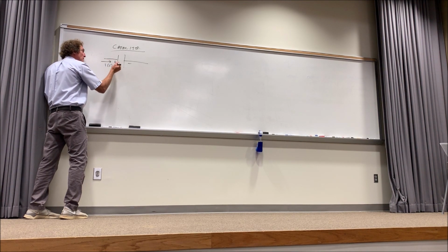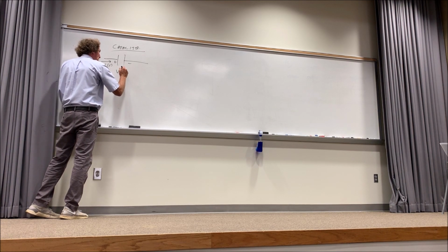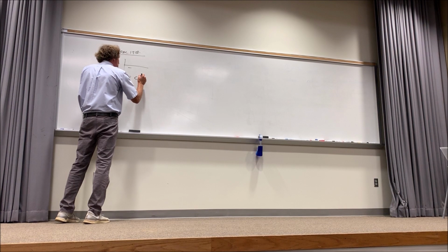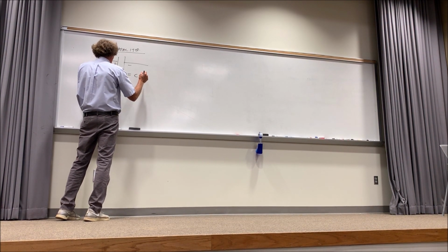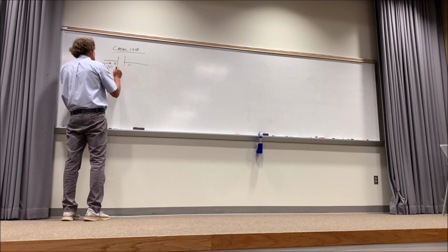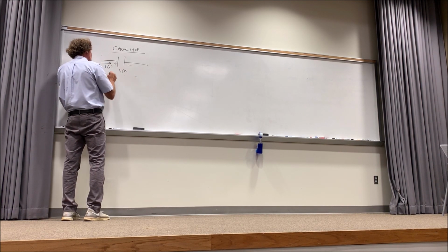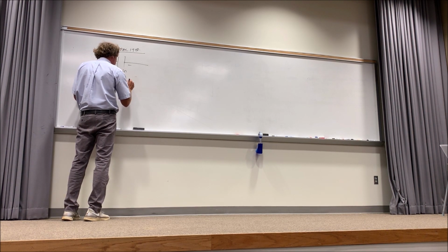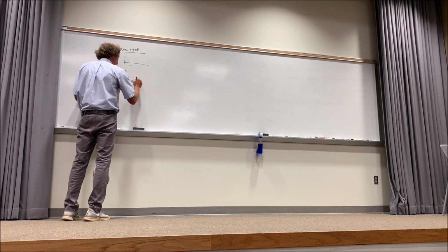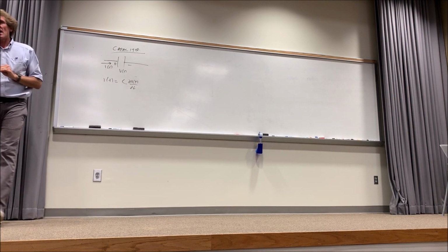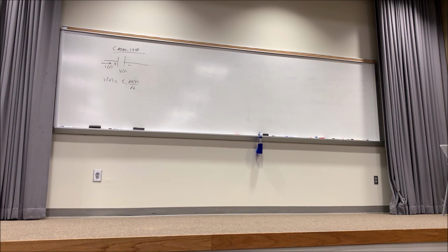And if such, the voltage that would be developed, V of T here, would be equal to C times the derivative, the current, my bad. The current, if this is a voltage here, V of T, and a current I of T, would be equal to C, the value of the capacitance, times the time derivative with respect to T of the voltage across that capacitor. It's I equals C dV/dt. Follow me on that, everyone?